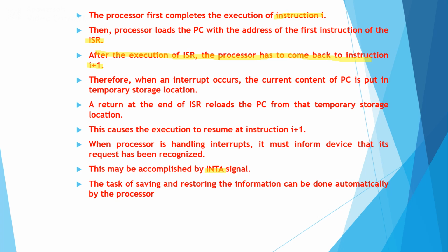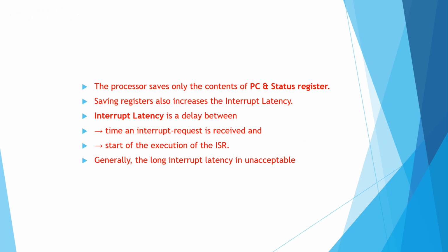The task of saving and restoring the information can be done automatically by the processor. The processor saves the content of PC and status register. Saving registers also increases the interrupt latency. The interrupt latency is the delay between the time an interrupt request is received and the start of execution of the ISR.